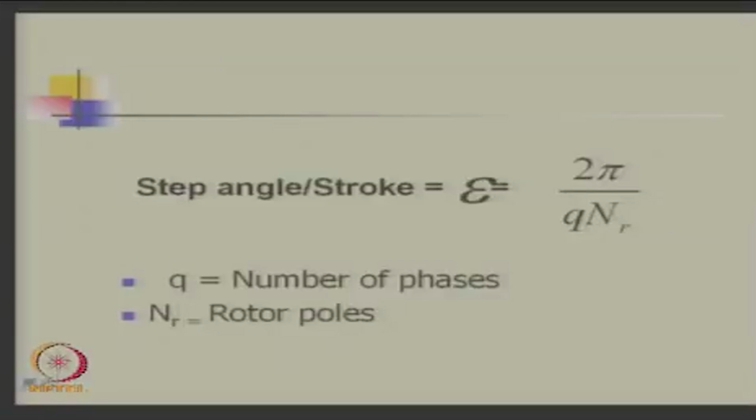As we do in stepper motor, we can use micro stepping, means simultaneously energizing two phases. Can we do it here? If you energize two phases, the magnetic field will be a resultant of this, and you can do it, but it is generally not done because it will complicate your controller. Because sir, if we do that, then the torque precision will minimize. Yeah, that is true. But since you are working at high speeds, you have to see the possibilities of this.